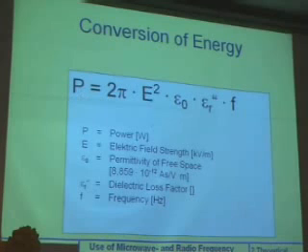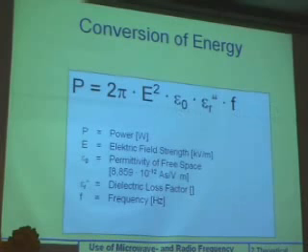And you see that we have two factors, E square and f, which are influenced by the technical equipment, and the other two factors, epsilon 0 and epsilon R2, are affected only by the material. So the material decides how microwaves work in the material, and from the technical point of view we have two possibilities to influence the power and the capacity of the electromagnetic field. This is E square and f. E square, the electric field strength, is given by the system. You have to calculate it very severely, because if you provide very high electric field strengths, you get lightning in a microwave system.